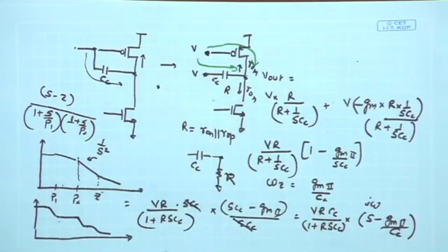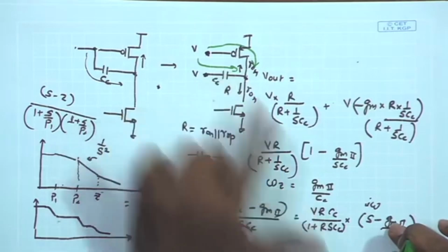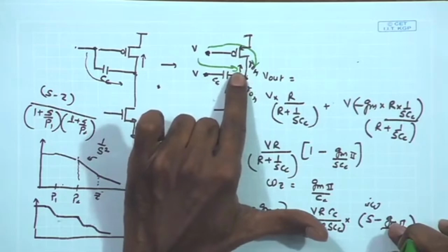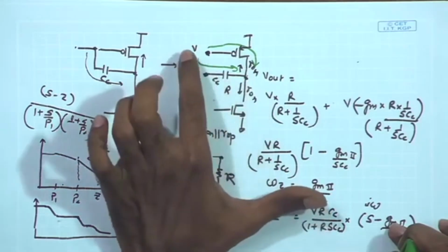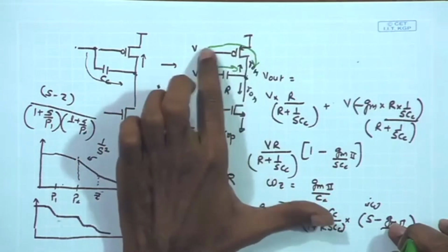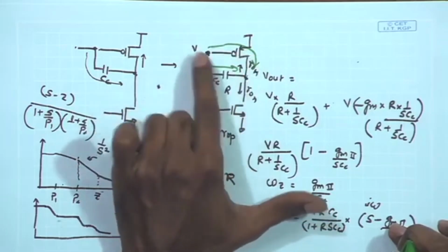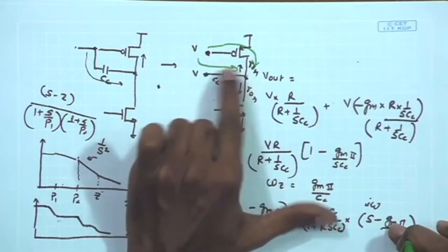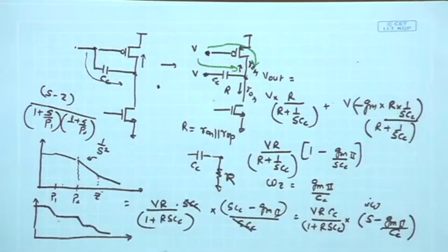That is one strategy, one possible scheme used to compensate this kind of circuit, and in order to do that we can think of inserting some component over here which can block the second path. So, basically we want to eliminate the signal transmission from the input to the output through one of the paths. Of course, this is not that path because this is the amplification path, we do not want to disturb this path, but this is an undesirable path through which the signal is propagating from the input of the second stage to the output of the second stage, and if we can block that, then we can succeed in our stabilization.